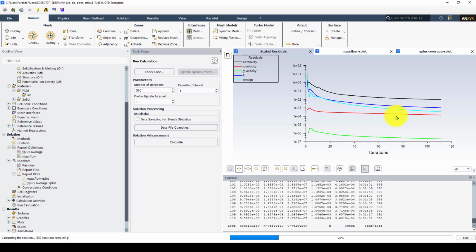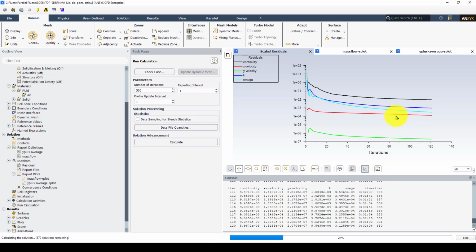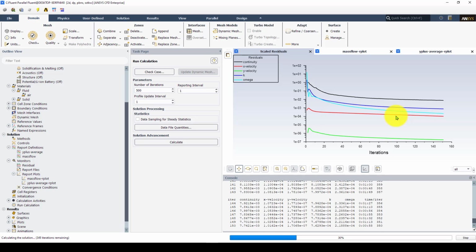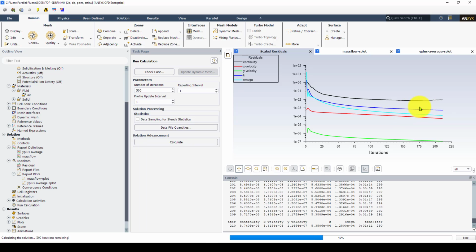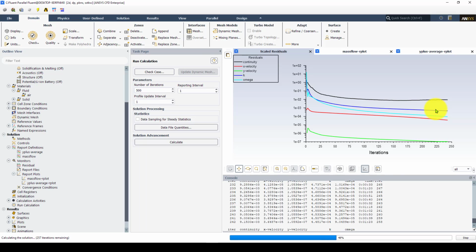So let's see how long it takes, or if it converges at all. It should converge. See that we have a large Reynolds number, 100,000. Then you can try to run at 10,000, 6,000, and you will see that it is much faster. And you can go laminar, a value like 4,000, and you will see that it will be really fast. So in this case, it's not converging. Okay, this doesn't mean that it's wrong, just that it's a really high Reynolds number.